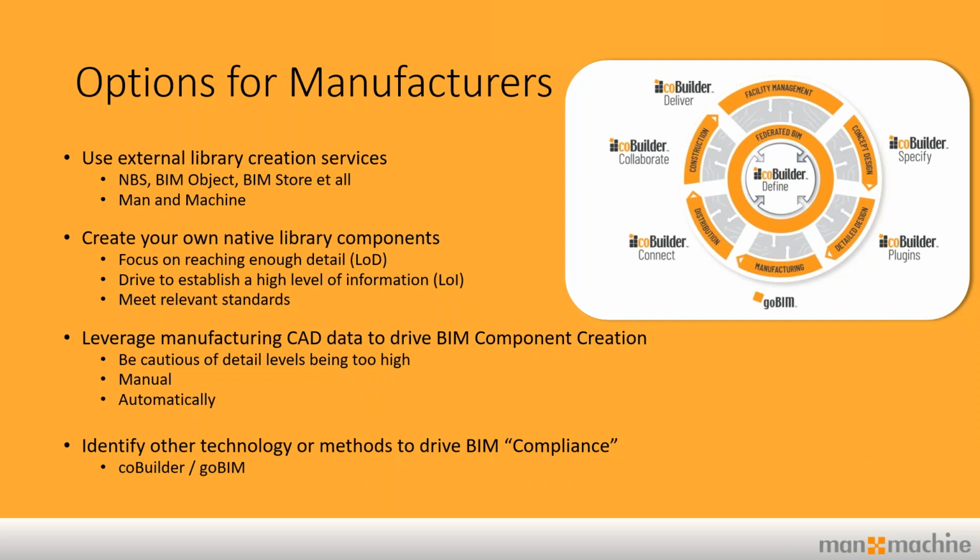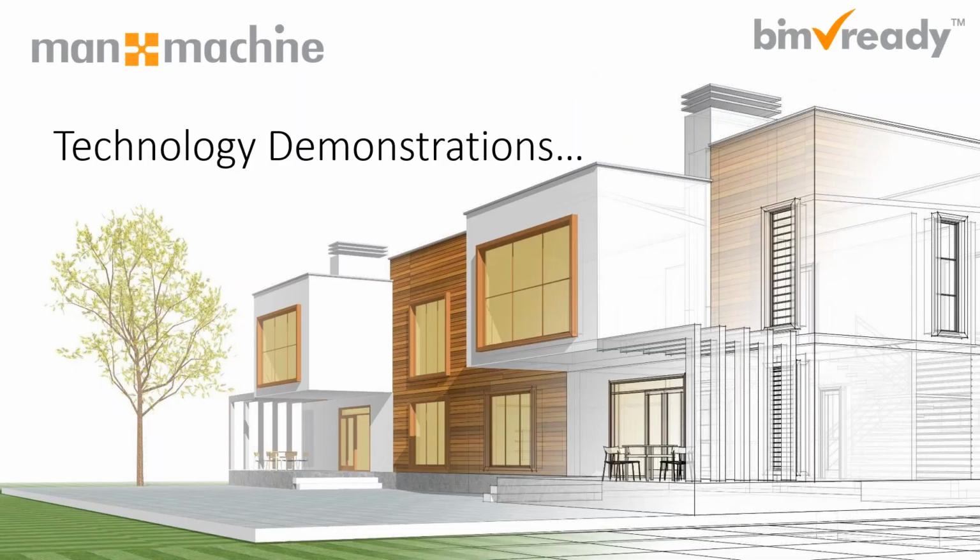What CoBuilder allows a manufacturer to do is throw a load of properties onto a cloud-based solution where Revit users can literally download those straight into a representative model in 3D. Again, hugely, hugely beneficial. But you've got to make sure in one way, shape or form that the information about both the use of the product, the access areas around the product is intact and is sent with those particular components.